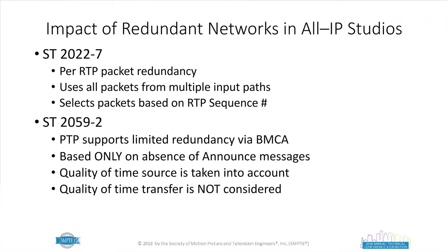Now, what happens in this case, and this is where it becomes interesting, because the IEEE 1588 specification doesn't tell you what to do in these topologies. Other industries have addressed it with very specific designs. In the power industry, they've gone and built an entire specification just around redundancy topologies. And we're now at this phase in these environments of what is it that needs to be done for PTP redundancy. So what's the impact here? As I was explaining on the previous slide, we use a sequence number for the -7, very basic. It's the same essence, it's the same packet, that's not a problem.